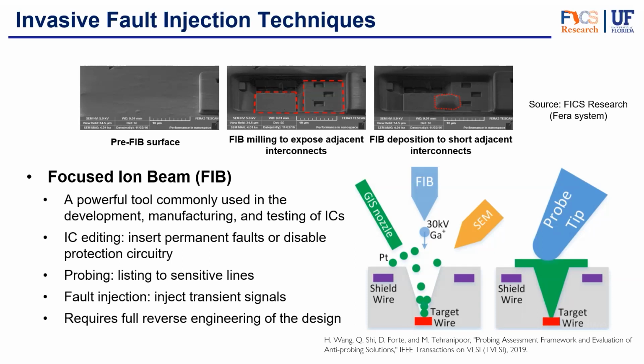Therefore, there is some delayering and polishing from the backside that should happen here. But at the same time, they are very focused and very precise about the location where the fault is going to be injected. The fault in such cases would be a permanent fault. In comparison with the last two previous techniques that we talked about, their faults can be transient faults, and they can happen at a specific amount of time.